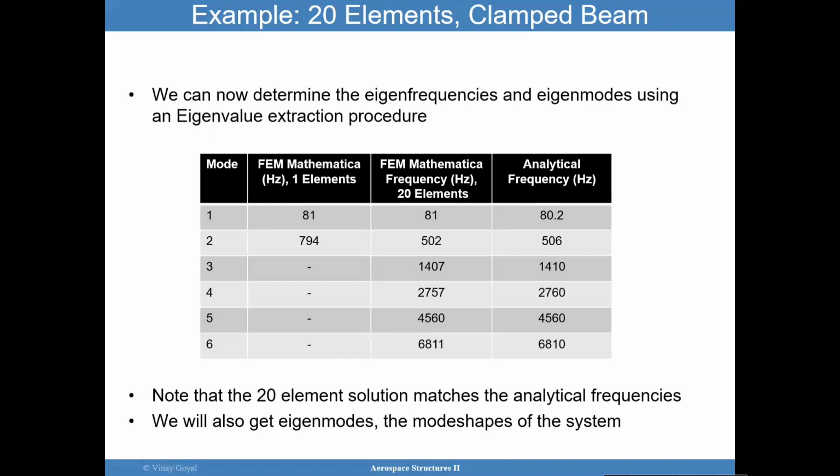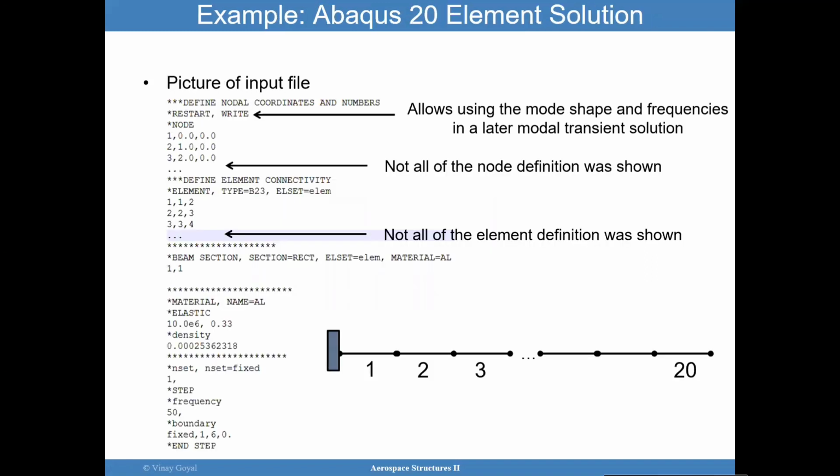So that's the point that I want to make sure you understand: when you discretize a system, you have taken a continuous system and discretized it so you have a finite number of subdomains, and as a consequence of discretization, that also turns the problem into a finite number of eigenvalues and mode shapes. So it's an approximation of the system.